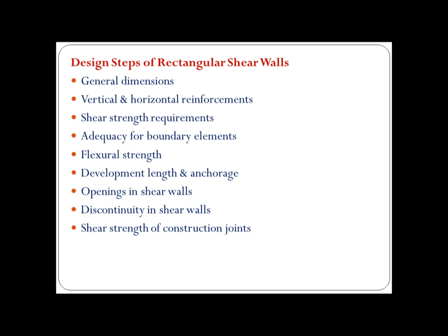And then calculation of development length and anchorage. In case we have openings, the openings should have some additional reinforcement, which has to be calculated. Any discontinuity in walls has to be detailed properly. And then shear strength in construction joints. Effectively, for examination design purposes, we will be stopping at flexural strength.